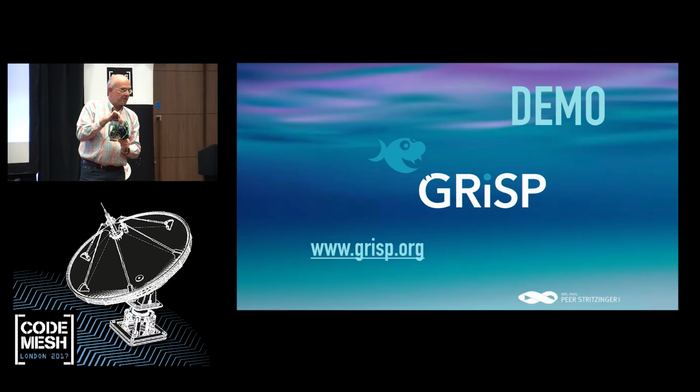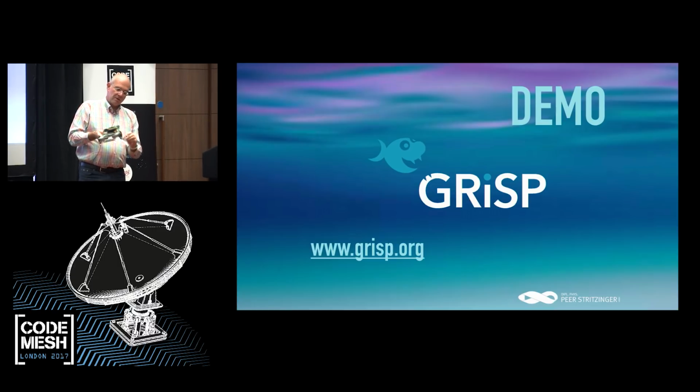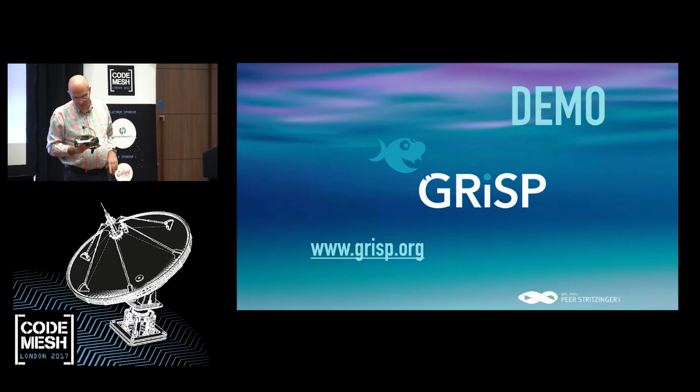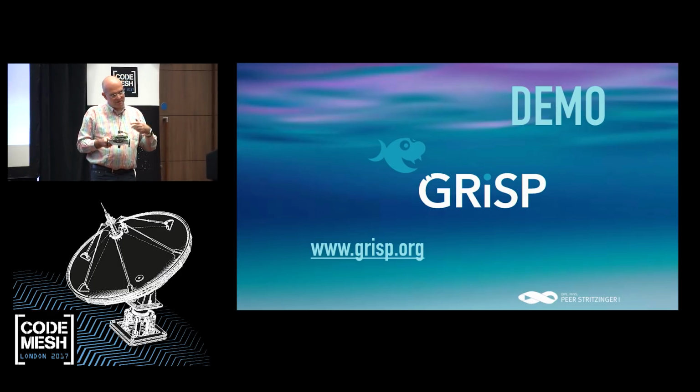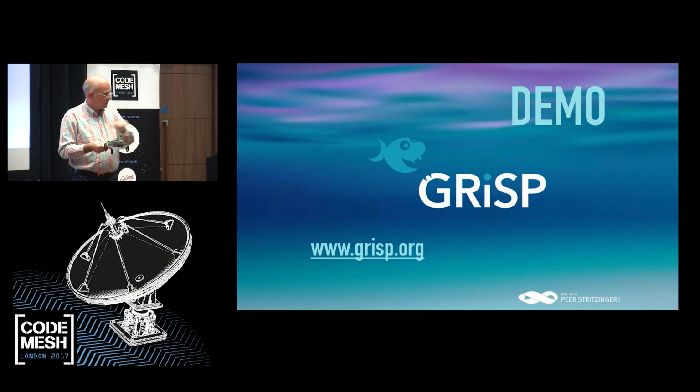And here we have the GRiSP board on top of it. And I have 2 batteries on, just for good measure. One 6-volt, just normal batteries for the motors, and a USB battery for powering the GRiSP board. So the battery is still full, that's good. I put the motors on an extra one, because the motors suck down the battery pretty quickly, and it sucks when you can't program because the battery is empty. But you could power it from both.